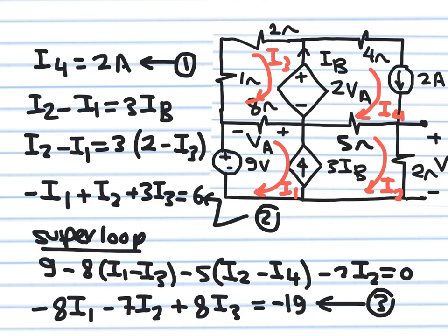Now, I got this equation from this current source, but I need a second equation. Why? Because this current source damaged for me two KVL equations in this loop and in this loop. As we agreed in class, whenever you see something like this, you build a super loop. So you bypass the current source by combining these two loops into one loop. We call it a super loop. So I'm going to write now KVL around this loop here, in the clockwise direction.